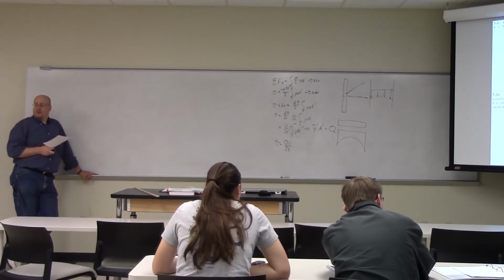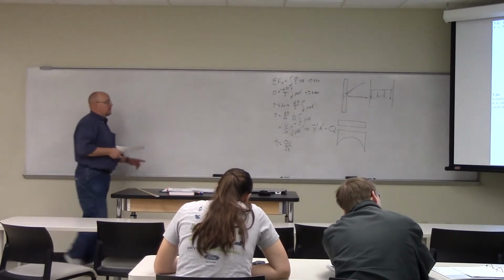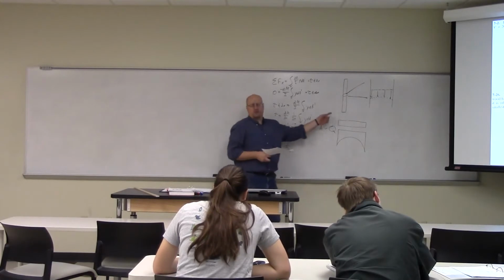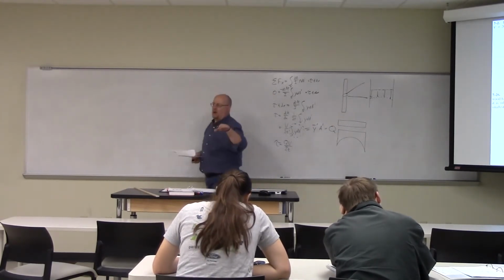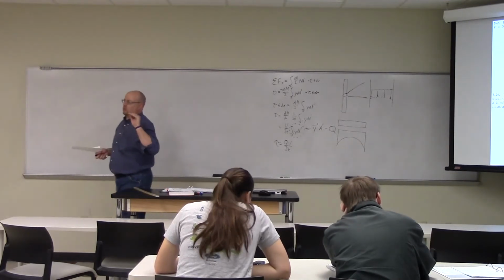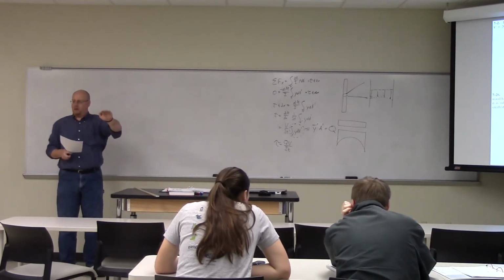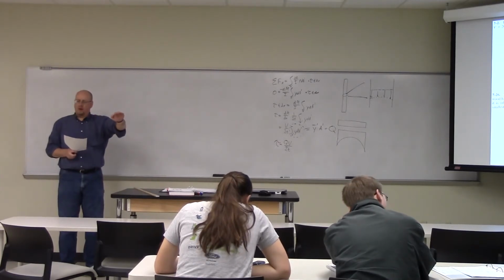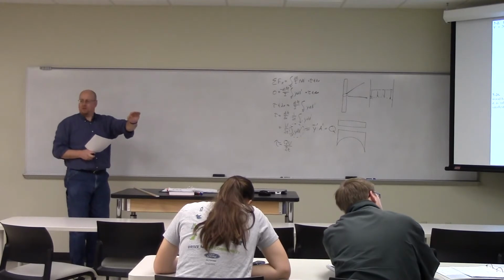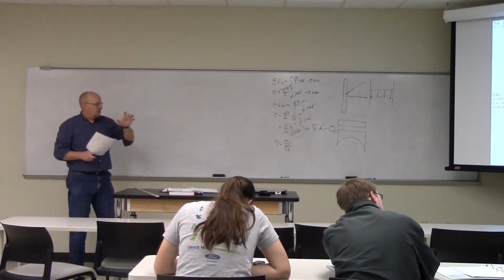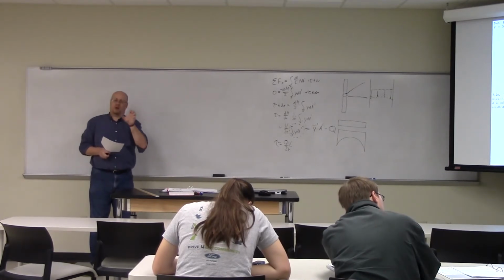So if we're trying to find the maximum shear stress, which is what we really care about, a lot of these assumptions we don't have to worry about so much, because most of the time we're only interested in the maximum shear stress. We don't care if there's a smaller shear stress up here, because the thing's going to yield because of the maximum shear stress. So we can deal with some constraints as long as they don't apply at the location of the neutral axis.